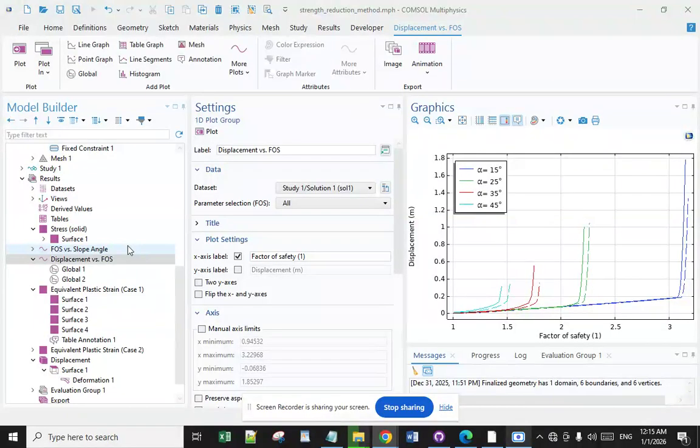Pressure vessels use 3.5 to 4, automobiles use 3, and aircraft and spacecraft use 1.2 to 4, depending on the application and materials. Ductile metallic materials tend to use the lower value while brittle materials use the higher values.